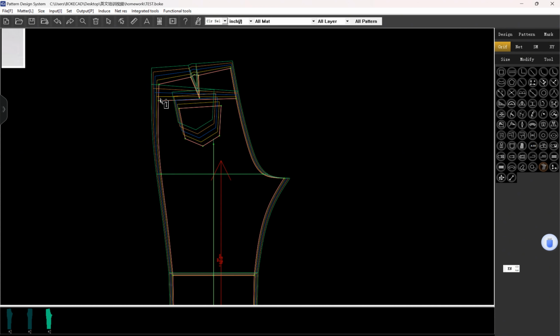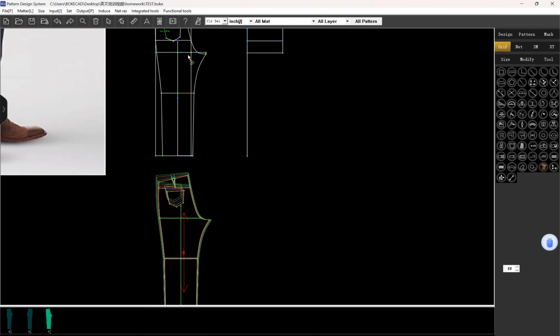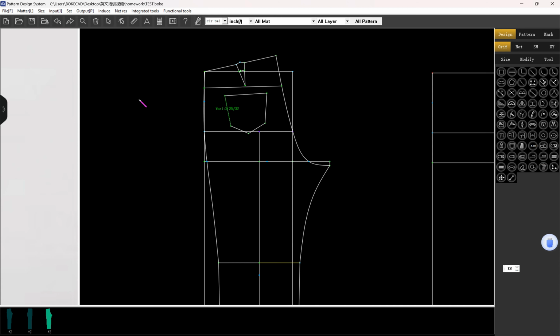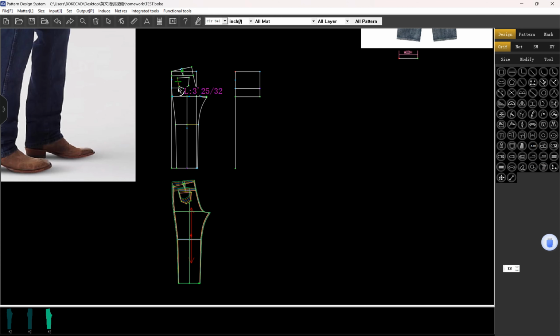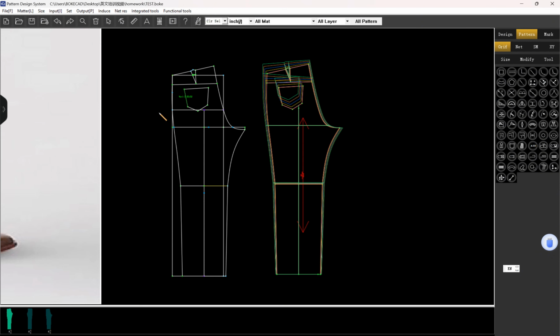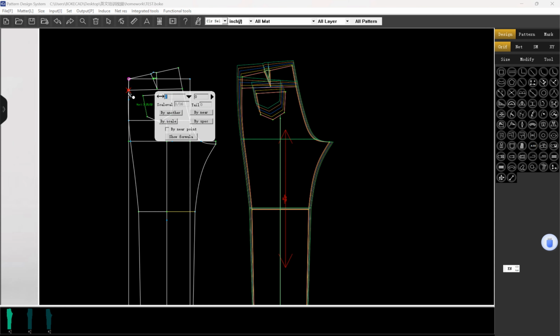So this part, the grading has some problem because the line we made here has different reference points. Now, as we can see, we delete it here and put it back to the pattern mode, select into here, and back to the design mode. I right click on the line. We can see the reference point here, so the difference also references this point.